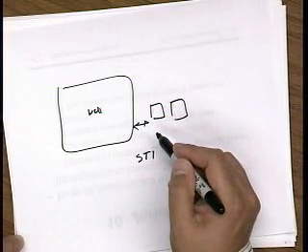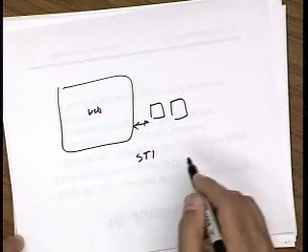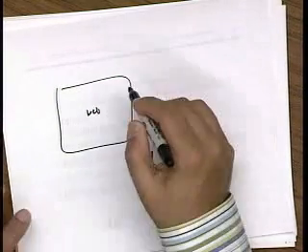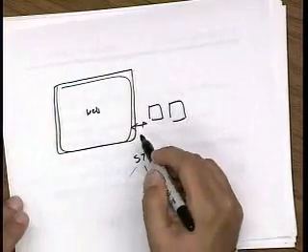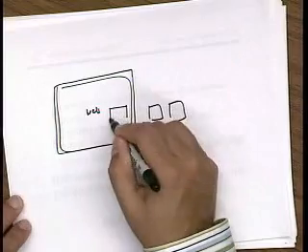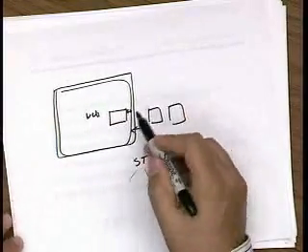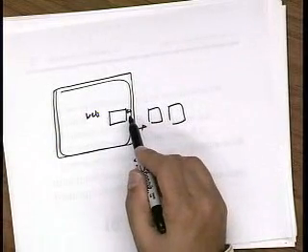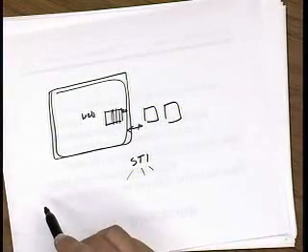So what does STI stand for? Shallow trench isolation. So it's the shallow trench that surrounds this device that actually creates stress. Devices that are first of all close to the edge, there's a design rule that says you can be so many microns away from the edge. Well, don't take that minimum, because the device on that edge is going to get stressed. Okay.